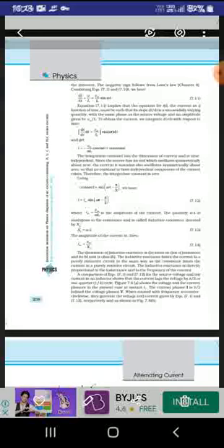Thus we get it, and the SI unit of XL is ohm, as you all know. The inductive reactance limits the current in a purely inductive circuit, and here you can see we have to put pi/2, or a quarter cycle, as the phase difference between voltage and current.